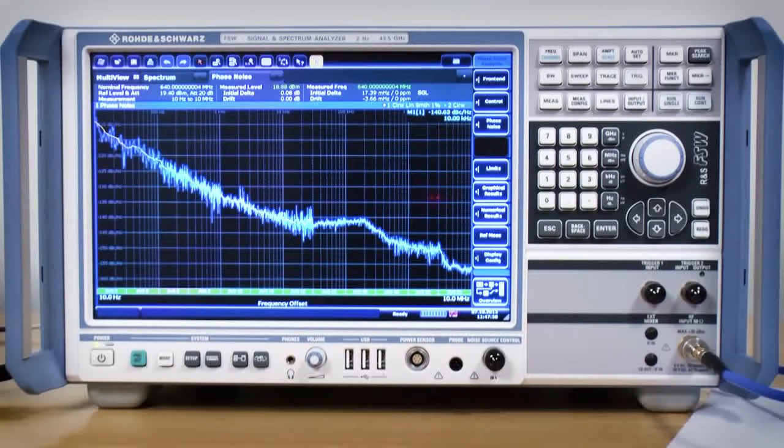One important point to note is that on a spectrum analyzer the phase noise is measured against the analyzer local oscillator. Any noise on this oscillator will be superimposed on the plot. Therefore the oscillator should have a noise performance better than the signal being measured by about 10 dBs. Other techniques like cross-correlation are present in phase noise measuring systems, and this overcomes the issue. But these systems are normally very specialized and much more expensive.